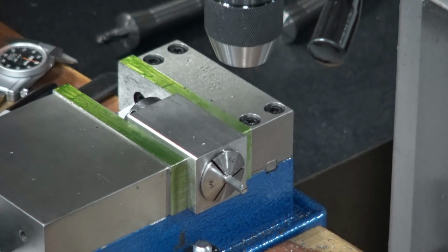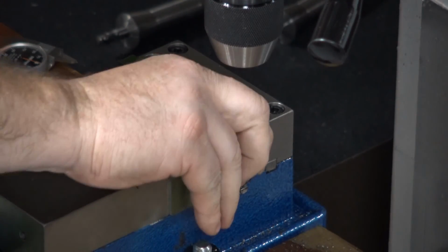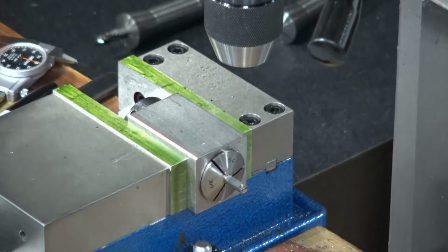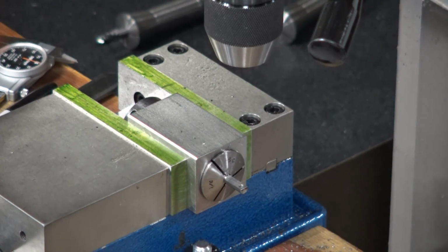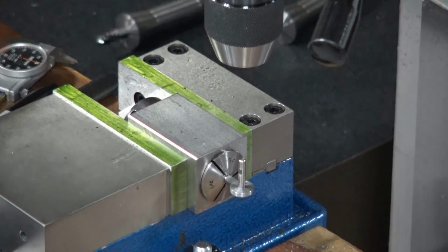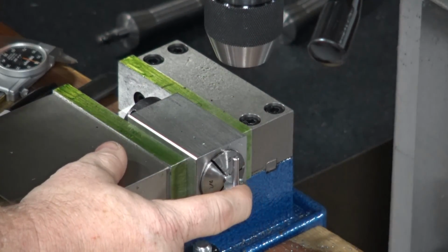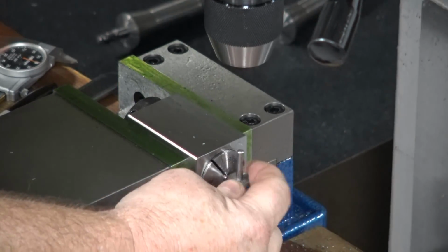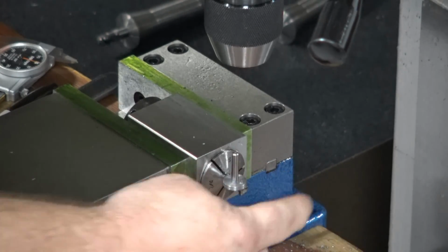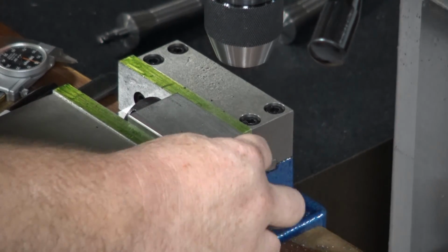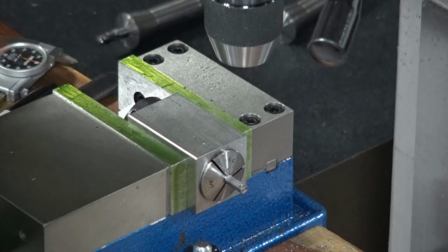While it's in the machine, I'm going to take my countersink just by hand. I'm going to spin it in that hole. So I've deburred the top side. We said that we wanted to do an inspection, not a visual or measurement inspection, but we wanted to put our crankshaft down inside the hole, and we want to spin the crankshaft 360 degrees. If the crankshaft does not clear, we're going to have to remachine that step, but this clears just fine. I feel really good about that.